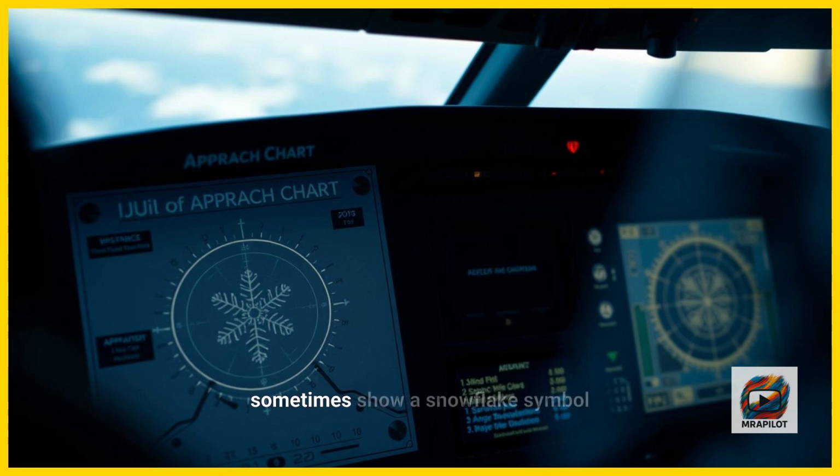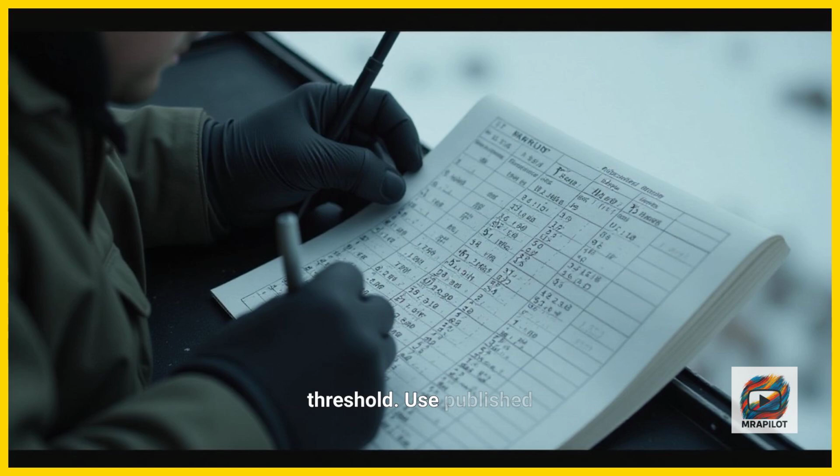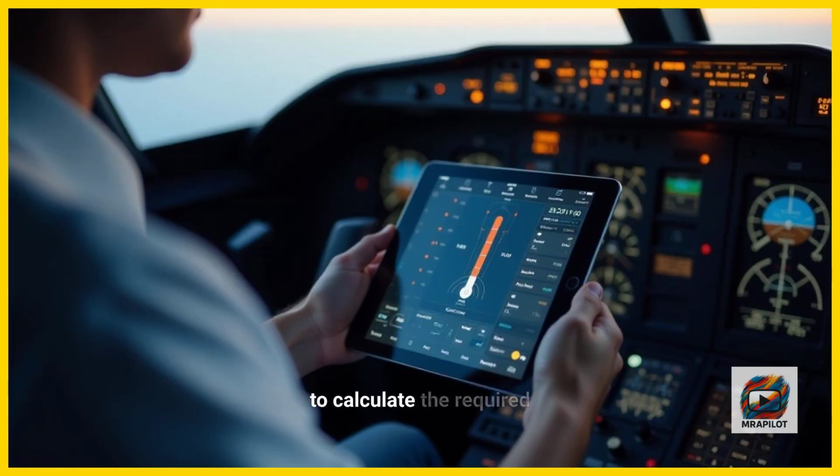Approach charts will sometimes show a snowflake symbol indicating that you must apply corrections when temperatures fall below a certain threshold. Use published tables or approved apps to calculate the required adjustment.